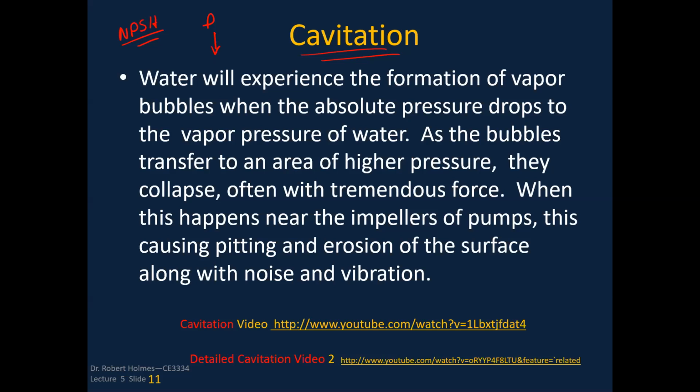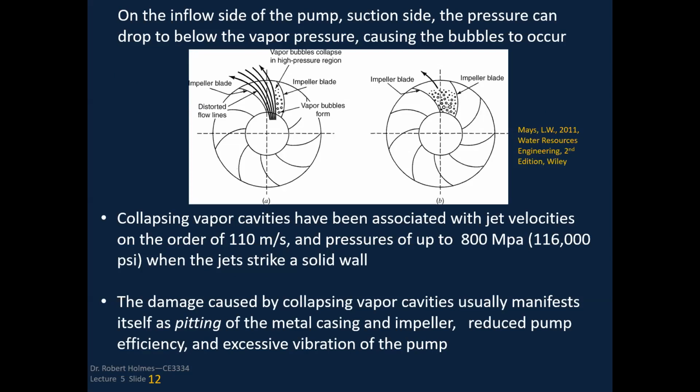And if those pressures go below what we call the vapor pressure of the water, then that water will instantly turn into vapor. And then as soon as the pressure rises a little bit, that vapor bubble collapses. That's called cavitation. I've got a couple of videos that you can watch to understand cavitation a little more. This slide talks about the dynamics in terms of the pressures and the velocities.